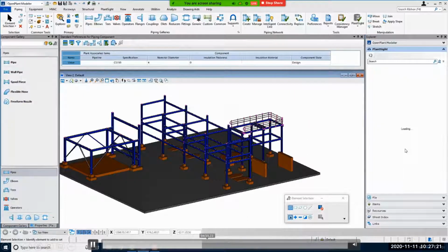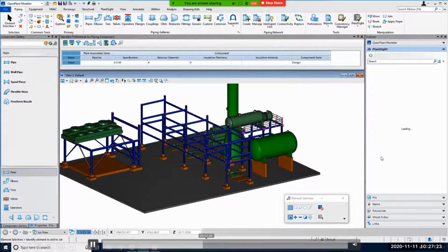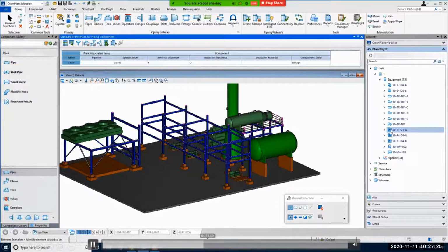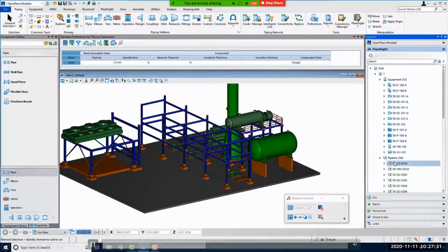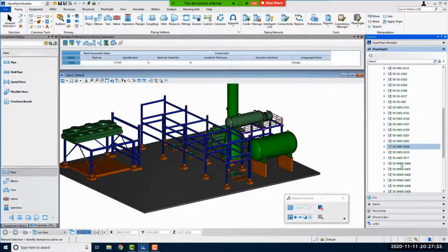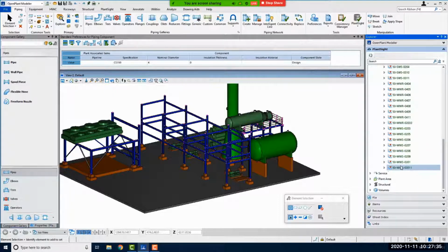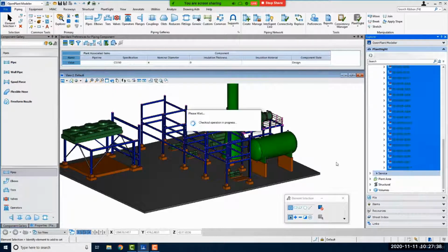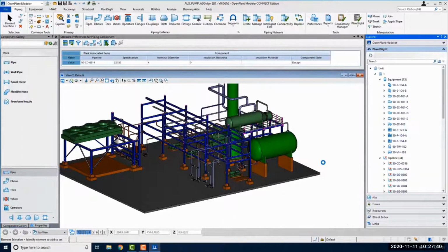So just now we added the additional parallel pump in PNID. Now the user goes into OpenPlant and makes those additions as well. And once you add it in the PNID, you understand that the tag was created, and the information related to the additional pump was in the database. Now in 3D, it can utilize the same information, and all you need to do is just add the physical location of that parallel pump. You don't have to enter all the information again.